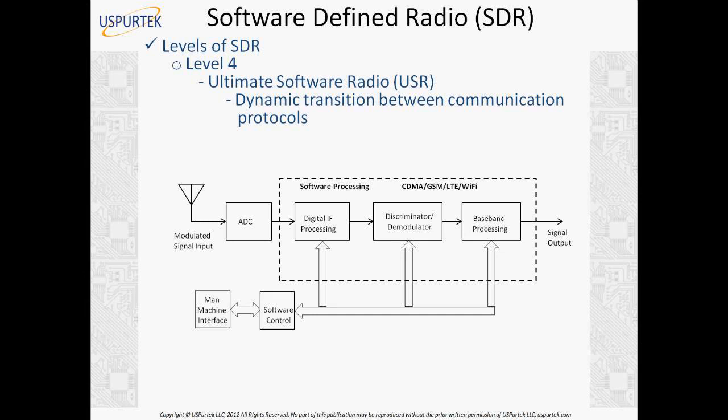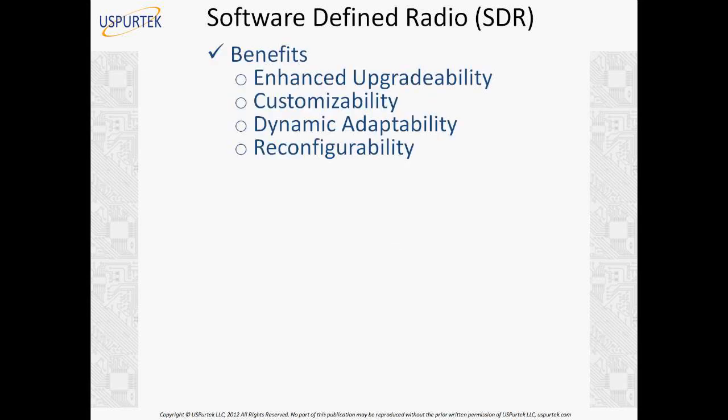Well, so benefits. What are the benefits of SDR? Enhanced upgradability. It's very easy to upgrade now because you are just upgrading the software in most cases. Of course, sometimes you will see, okay, I have new software, now I need to upgrade the hardware too. But what will be the upgrade in hardware? Hardware, you will need more capacity of DSP or more capacity on FPGA or the ASICs. But the most value addition will be in the form of software.